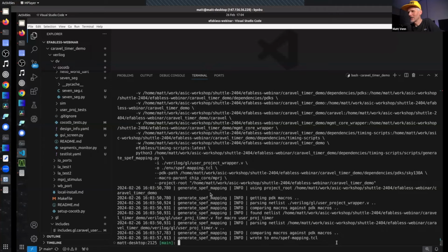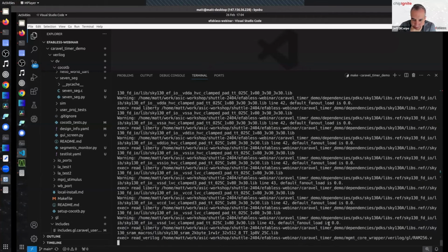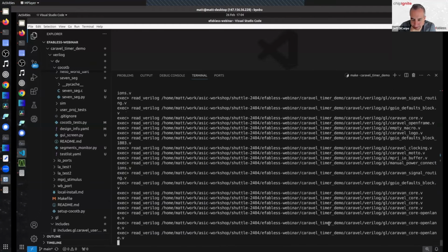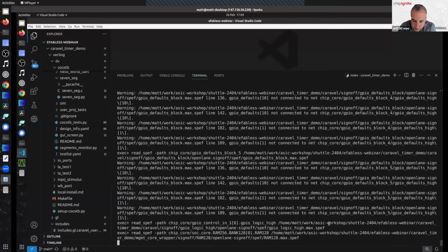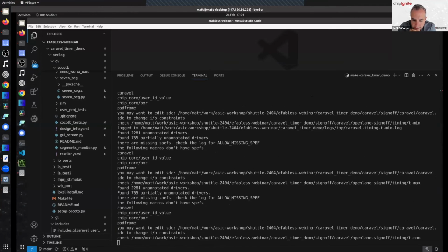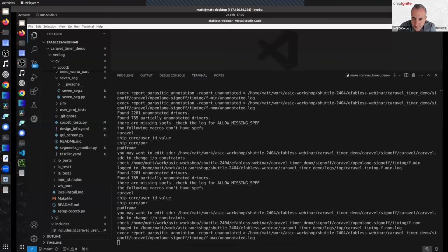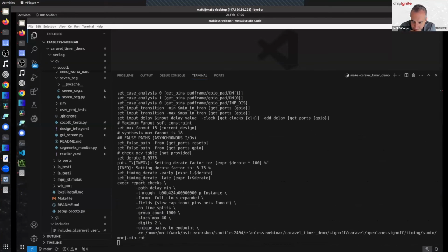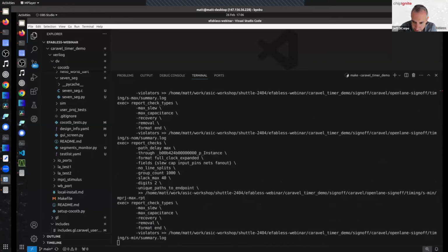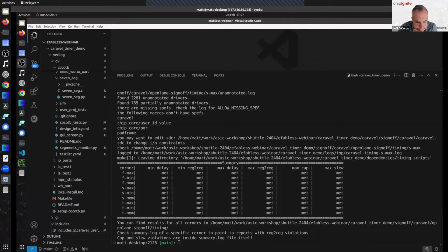While you do that, we'll look at the next exciting step of the journey now that the spec has been mapped. If you're not familiar with these terms, this step is STA, for static timing analysis. This is checking the timing of digital signaling within the chip, ensuring that the data is valid within the appropriate window for the clock. When we talk about SPEF and extraction, it means looking at the final layout, final positioning, and final wire lengths and widths, and pulling out all the parasitic parameters, the resistances and capacitances associated with each of those wires and connections, and incorporating that into the analysis to ensure that all the timing is met.